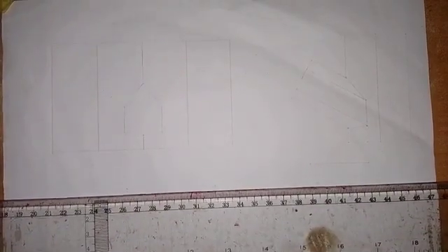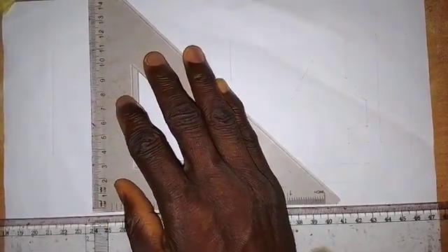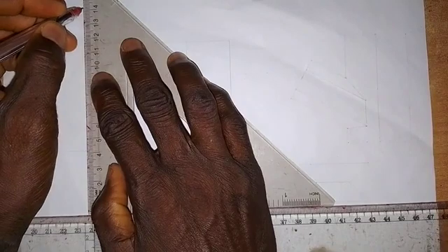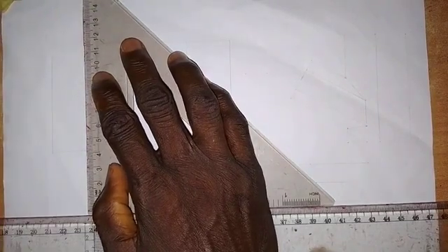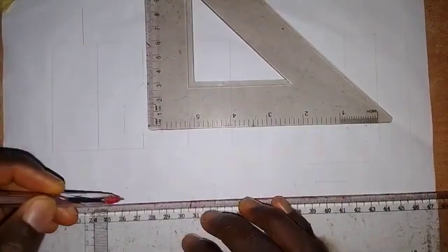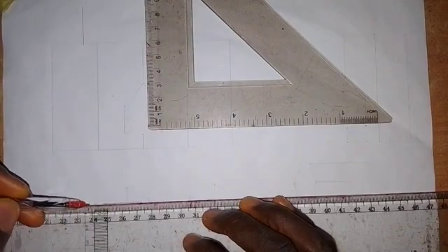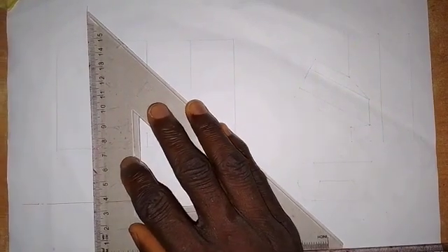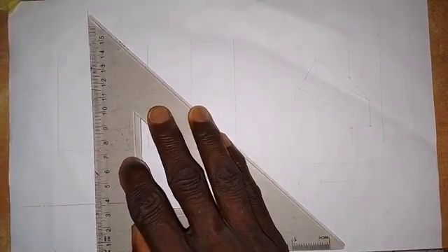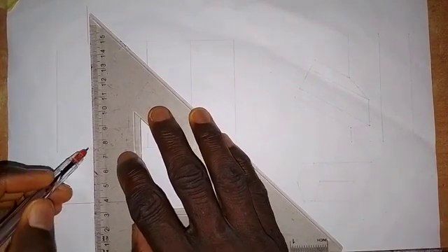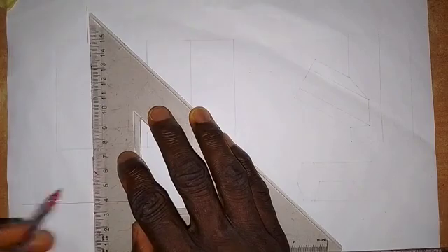So let's start. The first thing that we need to do is to produce the hexagon as we are given in the question. So we need to draw a vertical center line. Let me draw the horizontal center line for us to construct the hexagon. Then I will draw a short vertical center line, so I don't have to draw the whole of the vertical center line. I'll just take it like this.